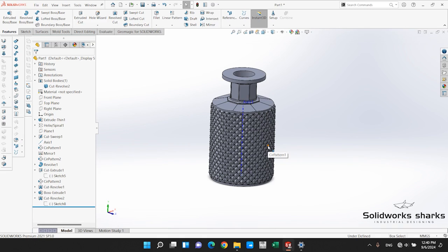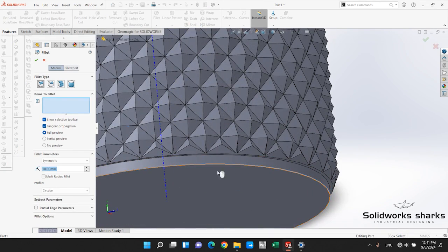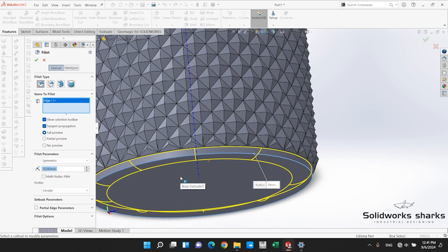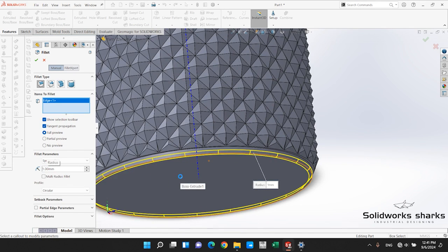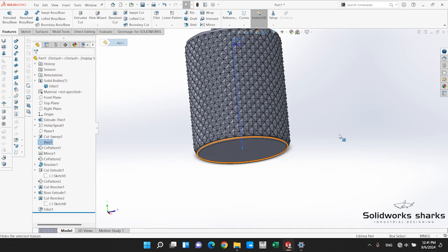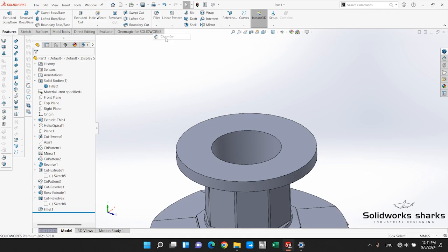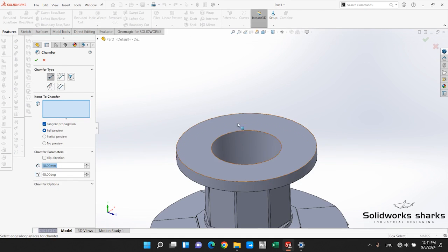And what we're going to have to do right now is fillet. So let's click on fillet, choose our base fillet and give it a size of 1mm fillet. So here's the first one. Let's again hide this one and go for another type of fillet, which is chamfer. It's not a type of fillet, just both commands are at the same place.